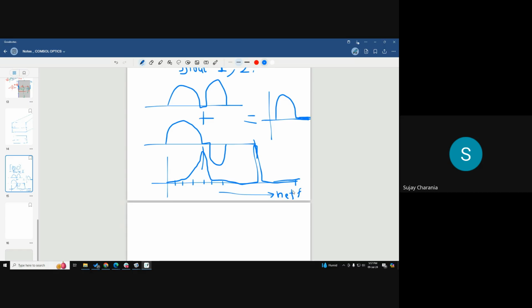My question is, a couple of minutes back we did this experiment where we found the non-fundamental mode, we found the effective index, and we launched that mode particularly. Now, generally, even if we launch one particular mode, it will excite other modes. So even if we tell COMSOL to only launch this mode with this refractive index, as we propagate through the medium, multiple different modes will be excited. So when we calculate the power, it won't be actually correct, right? Because some portion of the power will also be distributed towards the other excited modes. Is it correct to understand?